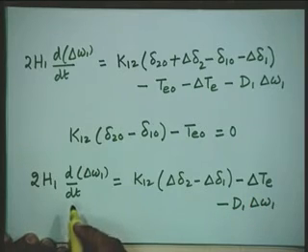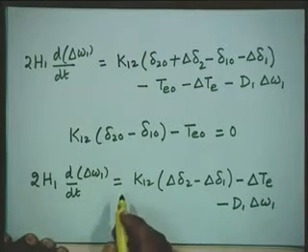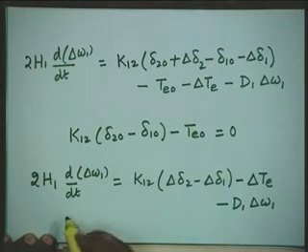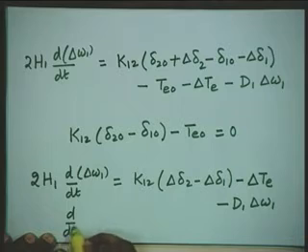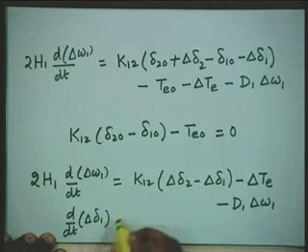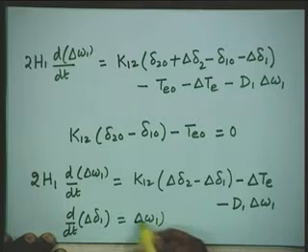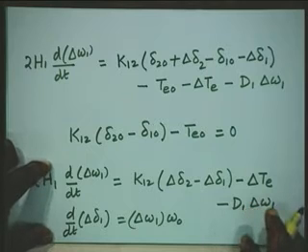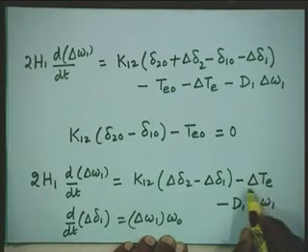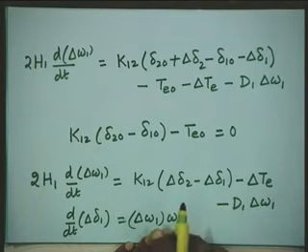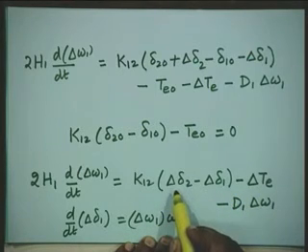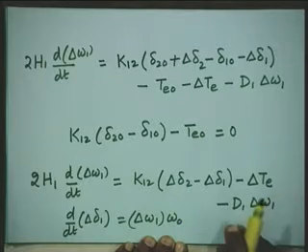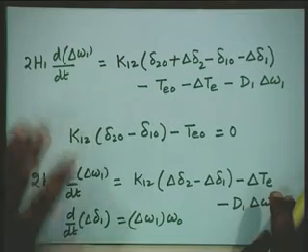Our second equation, when you write delta 1 equal to delta 1O plus delta 1, the linear equation will come out to be d by dt of delta 1 equal to delta omega 1 into omega 0. Therefore, these two equations are the linear differential equations. Now, here this torque delta Te is expressed in terms of the deviations of these angles delta 2, delta 1 and so on. It is a function of the deviation of the angular positions of the various rotors. Okay. Therefore, these two equations represent the linear differential equations.